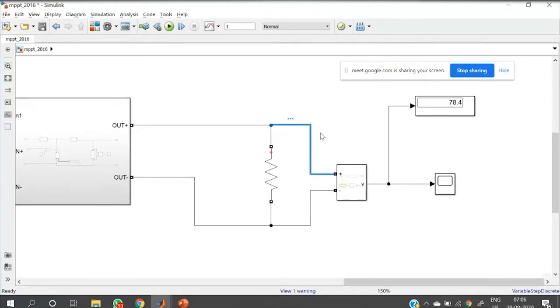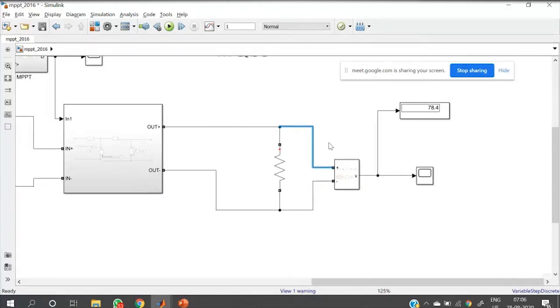Okay, clear. In that case, that 400 volt is maintained by the inverter, not by the MPPT controller. That voltage is maintained by the inverter by applying current to the grid. That means control is coming from left to right, not like an ordinary control system.